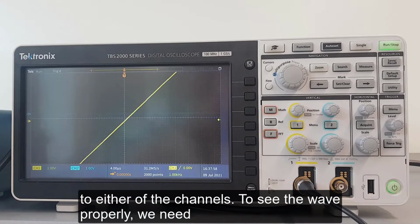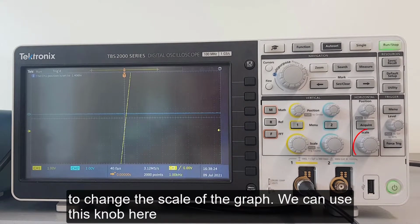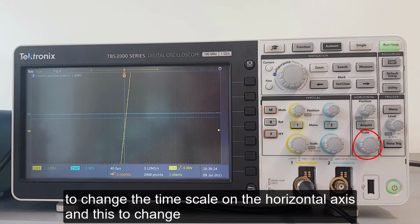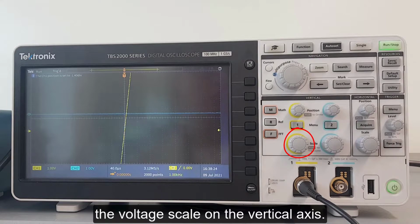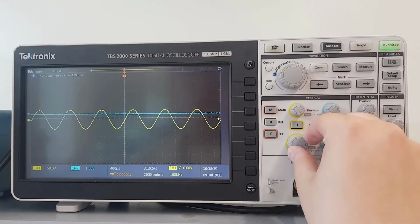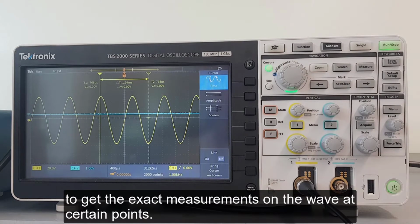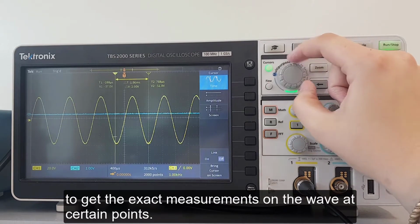To see the wave properly, we need to change the scale of the graph. We can use this knob here to change the time scale on the horizontal axis, and this one to change the voltage scale on the vertical axis. Now we can see the wave clearly. You can use the cursor to get exact measurements on the wave at certain points.